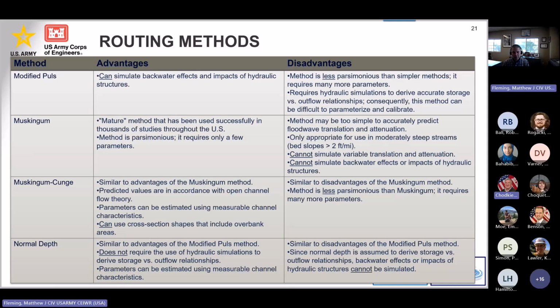You could probably turn the Muskingum-Cunge off and just use the lag routing or no routing. Or whenever you have some downtime, you could look at changing from Muskingum-Cunge to either Muskingum or the variable lag and K. If you make that switch, you're going to save a lot of runtime in the future.